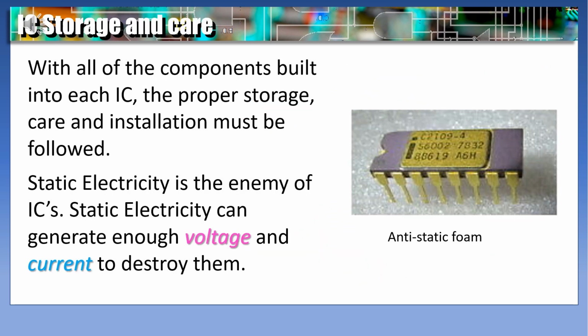With all of the components built into each IC, the proper storage, care, and installation must be followed. Static electricity is the enemy of ICs. Static electricity can generate enough voltage and current to destroy them.